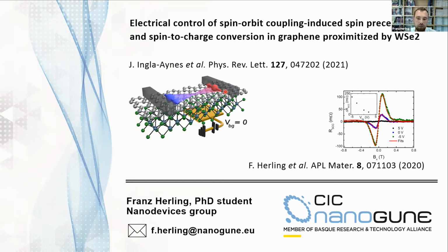The problem in a lot of graphene devices that we also run into in our devices is that you have a strong magnetoresistance if you're applying an out-of-plane field, which normally covers, even in the non-local geometries, your spin signals. If you've seen the scale, we're measuring here single milliohms, the spin signal in our device, and the resistance of graphene, which is a highly resistive material, is often in the kilo ohm range. So the ordinary magnetoresistance often covers your signal for the out-of-plane spin precession. But theoretically, it should be possible. You have to really design your device to make it possible.